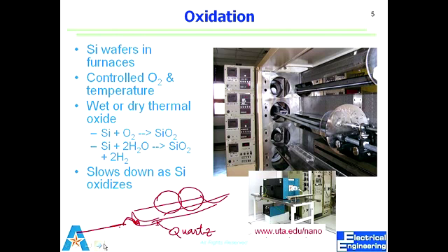This is just a picture, and probably won't be clear to you unless you see the system. But essentially, this is the loading area, and this is where the furnace is, probably 8 feet behind it. This is a smaller furnace, so this is the opening of that furnace. It is nothing but a glass tube which has a small opening, and then it's a continuous cylinder, closed from behind. We have an opening for gases in that outlet, and this opening is where you load the wafers.